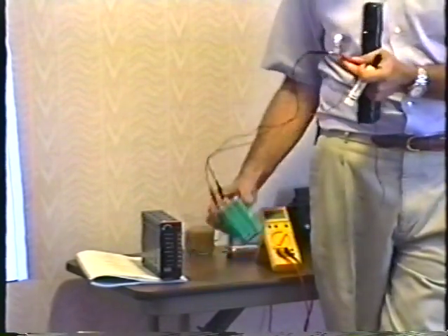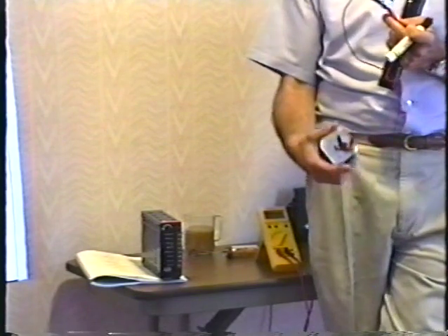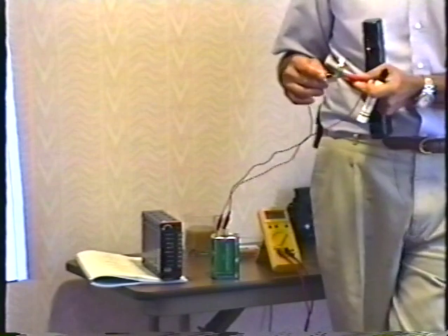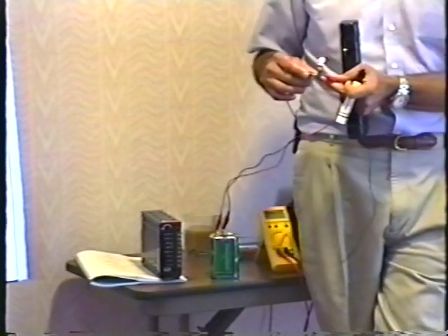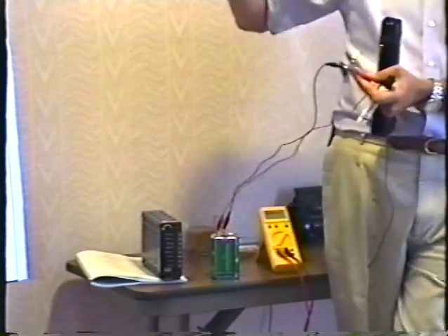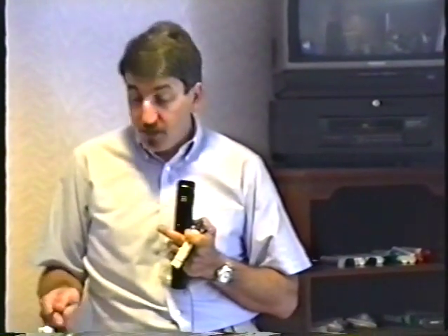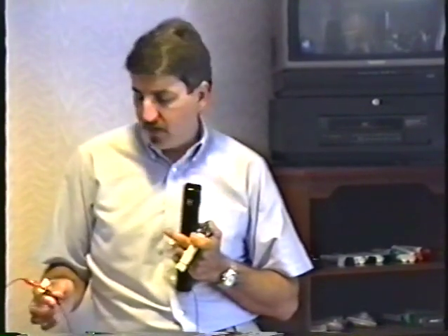But of course, if I tried to jump start my car with these little clip leads, they probably would look like that, wouldn't they? Because the starter motor in a car draws hundreds of amps of current, and it would just fry them completely. So theoretically a wire has no resistance, a theoretical wire. But we know, of course, that they must have resistance. That's why you use thick wires for some things and thinner for others, because you need to draw more current, let's say, for the starter in a car.